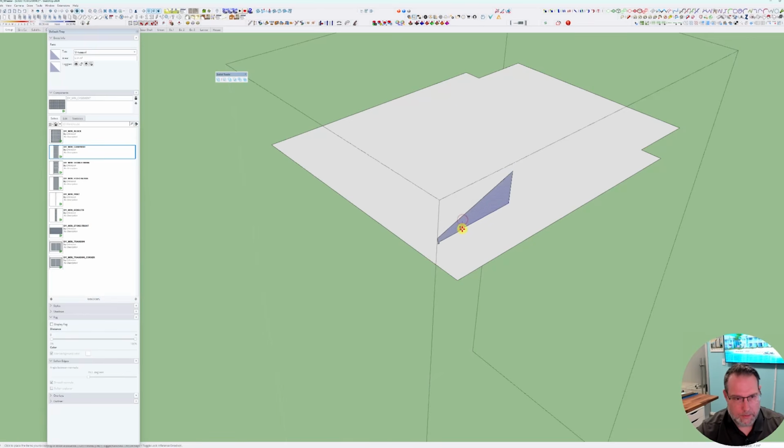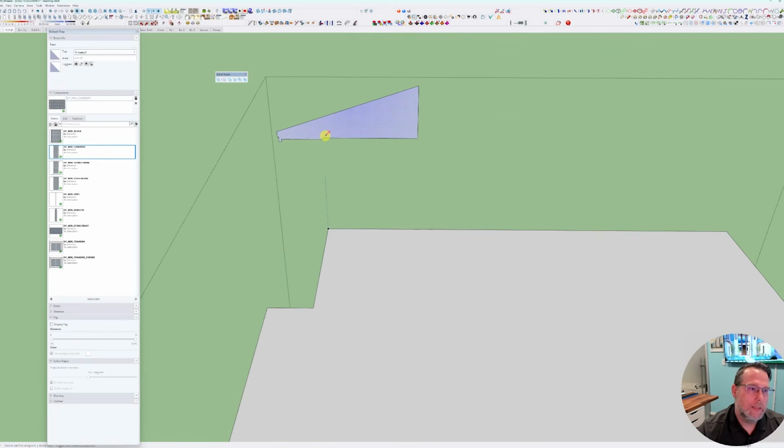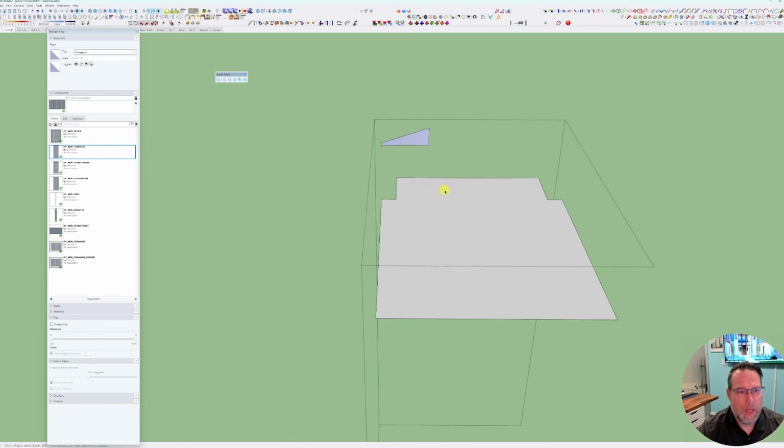And in reality to make this work, I want to move this guy here because this is going to be my starting point. I'm going to rotate it. So what's happening is this is my insertion point right here, and I have that perfectly aligned with here 5 feet above. I'm going to double click this to select all the lines, but I don't want this one here, so I'm going to do Control Shift, which will allow me to deselect everything else.